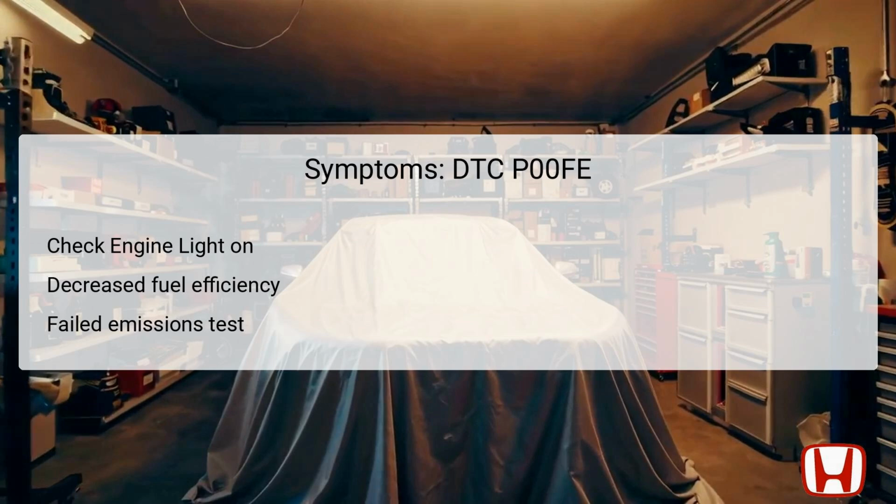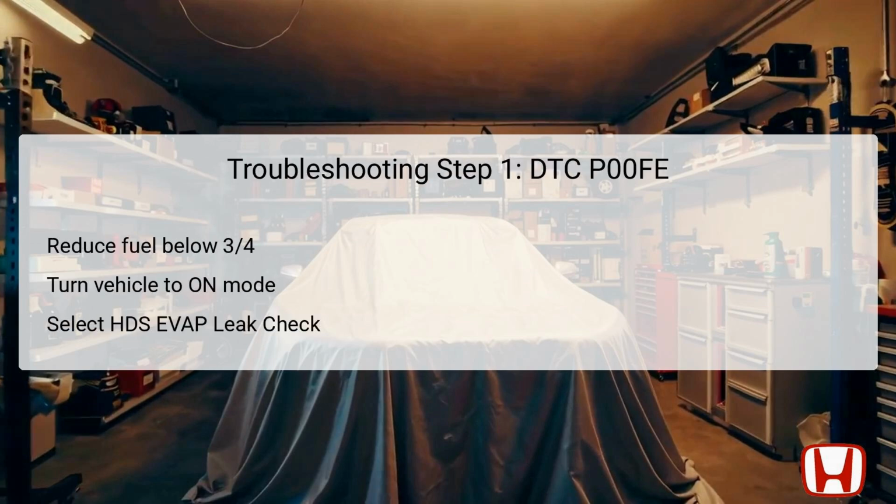Furthermore, if the EVAP system is not functioning correctly, the vehicle may fail an emissions test, leading to potential legal and financial repercussions. Regular monitoring of the vehicle's diagnostic system can help identify these issues early. The first step in troubleshooting DTC P00FE involves following a confirmation procedure. Begin by reducing the fuel level in the tank to 3/4 or lower, ensuring that the system can effectively undergo testing without excess pressure from fuel.